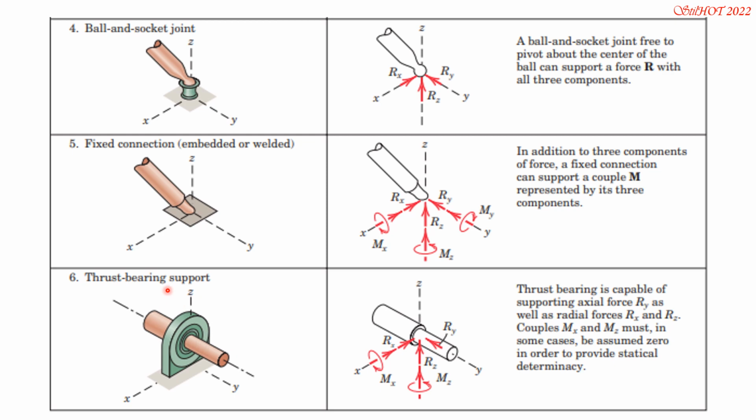Then we have thrust bearing support. There's no force along this direction, the three forces are present rather, and there's no rotation about this axis here.